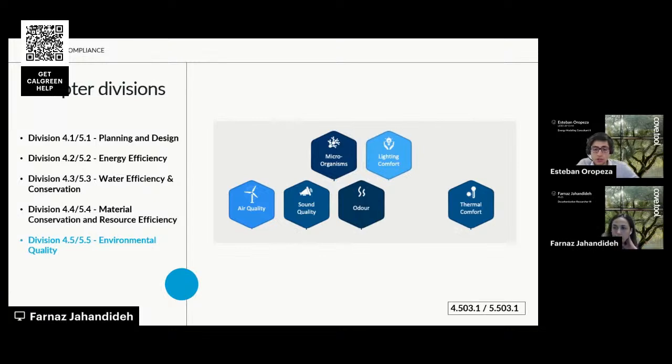Permanent HVAC system required MERV 13 for the ducts, and they need to be covered in tape or plastic during construction to avoid contamination. The focus here is having the ducts be delivered on site with end caps, so they're not getting construction dust.